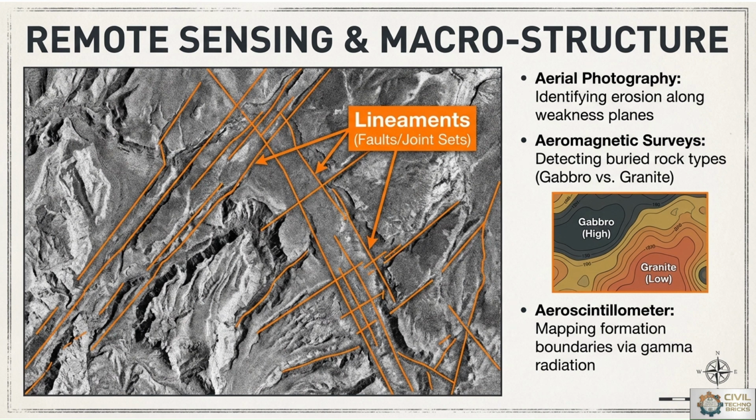So soil and rock properties directly influence highway foundation stability and pavement design, which will be collected based on the remote sensing technique. Weak soils may cause differential settlement and pavement cracking. Also, weaker rock plays the same role. Hard and stable rock is the most important formation, providing better support for highways and structures. Geological investigation helps us to select suitable construction material and stabilization methods.